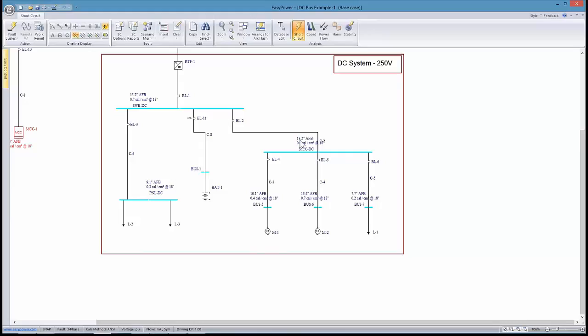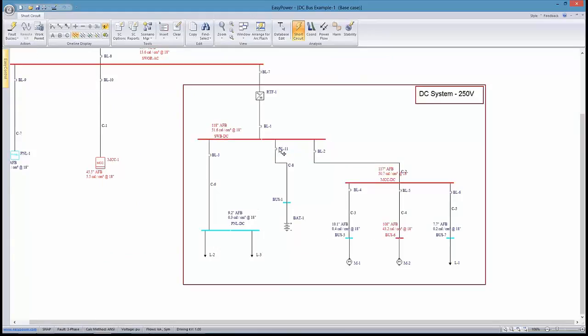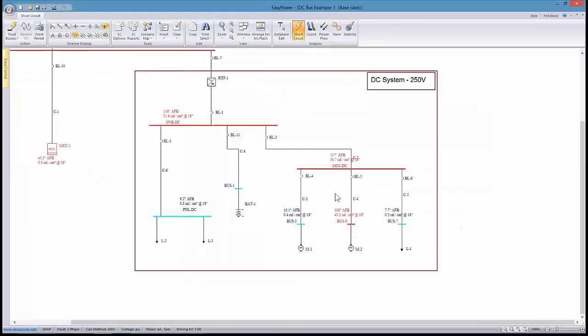And I've still got my breaker open. With the breaker closed, which means the battery's in the circuit, now I've got excessive energy on 3 buses, and so it begs the question, okay, was this the wrong breaker to choose, which it may be, and that might be the easiest fix, or are these incorrectly set?